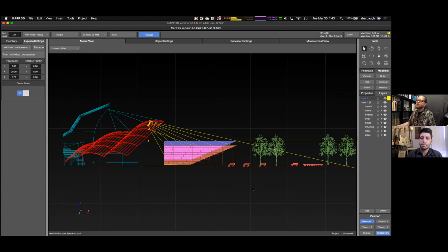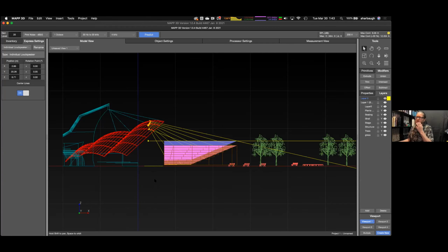One thing that I do fairly often, it's kind of hard to illustrate in this specific model, is I'll use that 6 decibel variance that we looked at, and I'll pop one speaker in that I want for a distributed array, such as a front fill array or an under balcony array. And I will just do one speaker and find out how wide 6 decibels of coverage is at the listener plane. And as I make an uncoupled array of those loudspeakers, that 6 decibel coverage is what I want my spacing of loudspeakers to be.